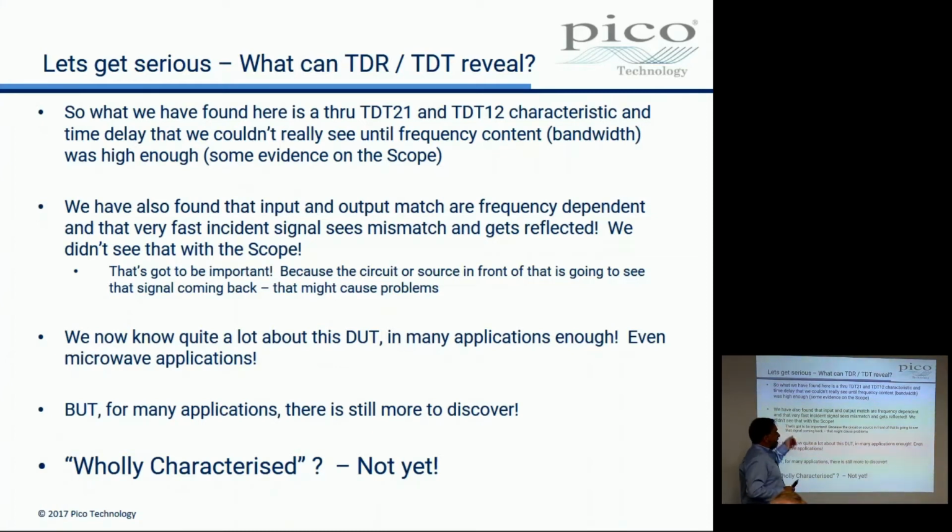Now that reflection might be quite important, because the signal coming back at the source could damage it actually. If the source is a reasonably high power amplifier and it's getting signal back that is double the voltage it sent out in the first place, ouch! Yeah? And this is what happens on the national grid at 50 hertz. So we send out 400 megawatts down a cable, 100 kilometers long, 400 megawatts flowing nicely, load is absorbing it, yeah?